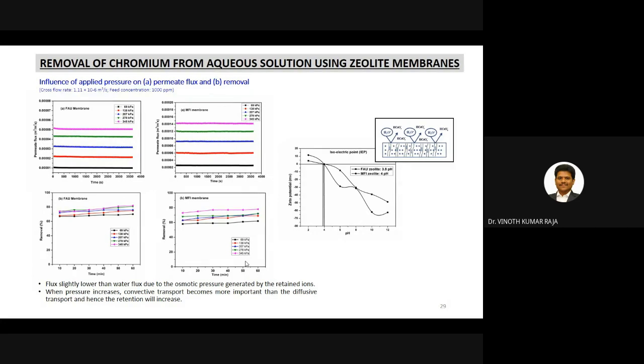But as I said, it can be carried out by having some composite membrane, such as zeolite composite membrane. So here I would like to point out that the surface of the membrane is the key factor influencing the removal efficiency. When the membrane is dealing with an ionic solution, the surface charge is a very key factor here. So even if the pore size of the membrane is larger than the solute size, in this case what we have been saying.